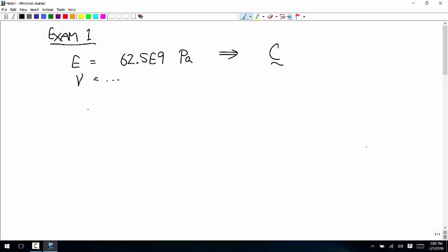And so if your Voigt stress is in megapascals, then your Voigt strain is going to be off by 10 to the 6th, by a million. You're close, but that's a pretty significant error if you're going to use that for calculations for building something.